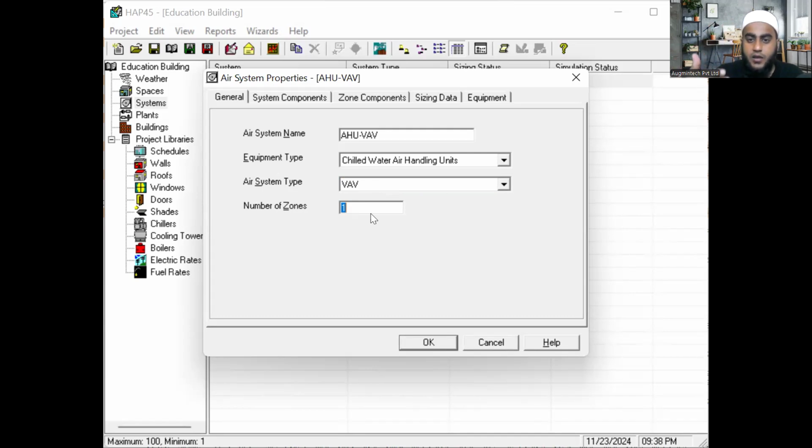Let's say in any room the temperature level goes down, because as per ASHRAE standard, I have also written how much temperature we have to maintain for human comfort, near about 76 °F. Due to any reason, let's say the temperature goes down inside the room, let's say it becomes 60 °F. At that time, the thermostat which you have placed inside the room detects it and gives the signal to the VAV box.